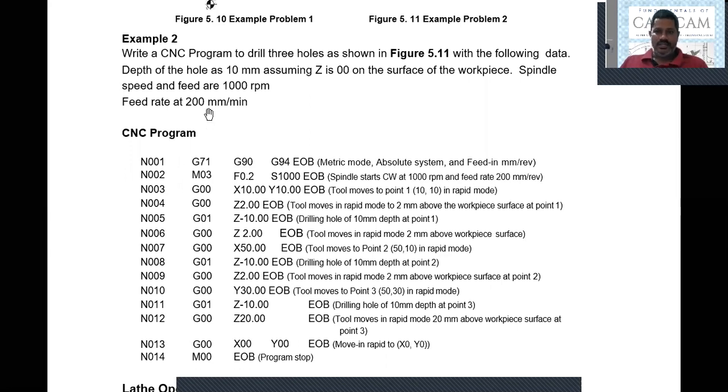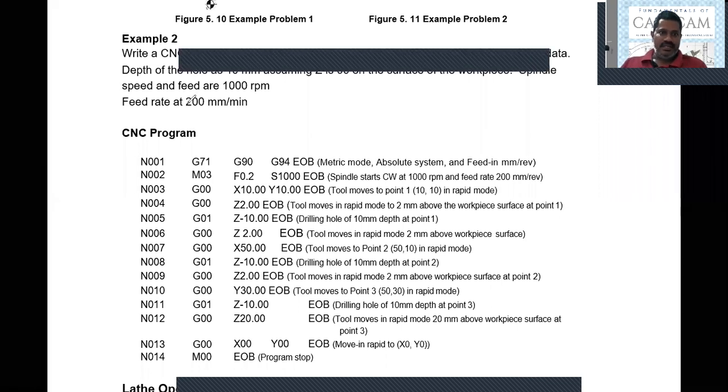So this value need not consider some value, mm per revolution, how much distance we need to move. So it should be 0.2. So can I take this value as 0.2 mm per revolution? So directly we can substitute that value here. Okay, so please correct this value.